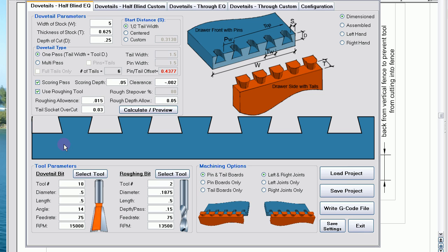And do not round off tool information, especially with dovetail bits, because the margin of error is very, very small with the dovetail bit. They need to be very precise. The smallest amount of error will show up in your joints. So do not round off dimensions when you're entering, say, an inch bit in millimeters, or the other way around.